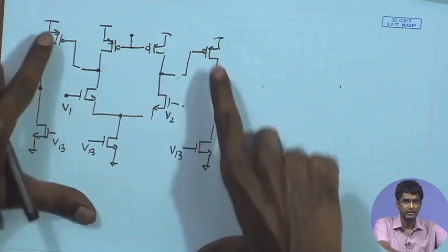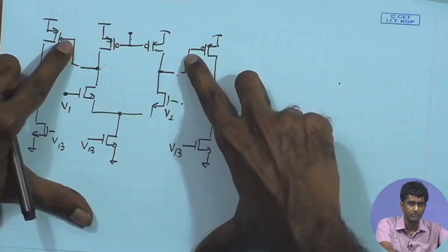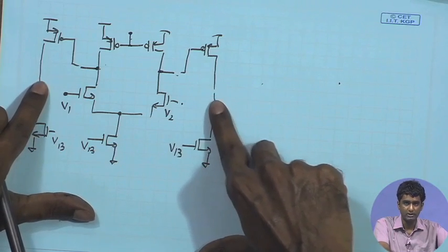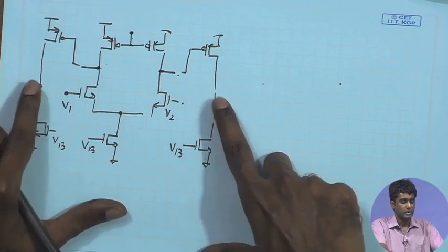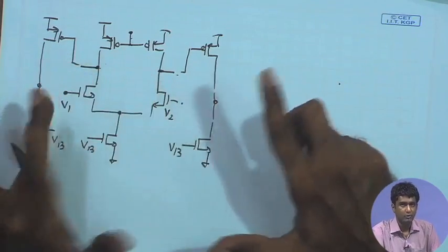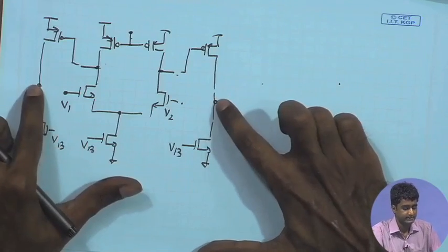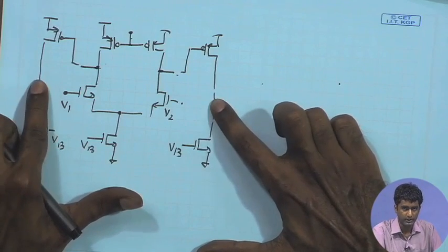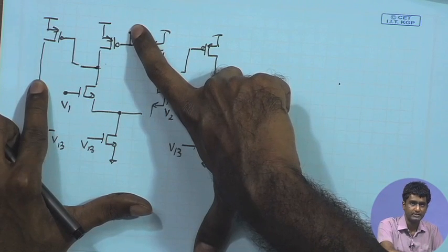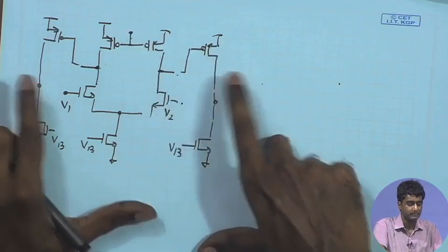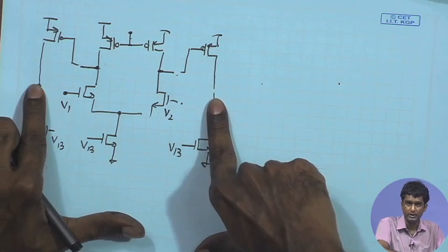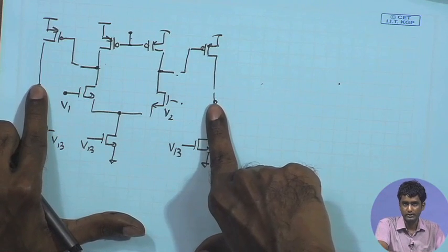So, this is a common source amplifier, input device, the load device, and therefore, the gain from here to the output is again Gm RO by 2, and these are also active loads, and therefore, we do not have a well defined DC point over here. So, now in this particular amplifier, how can we set the DC bias point for both the stages? One option is that we sense the common mode at the final output only, and then control the bias point of the PMOS transistor by the single error amplifier, assuming that it is going to set up the common mode level over here appropriately, such that the final common mode output is at the desired DC point. So, there is one option.